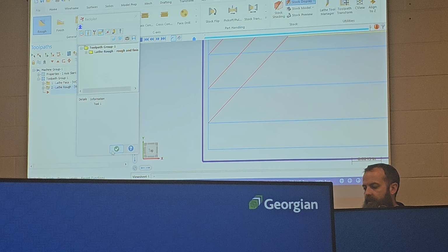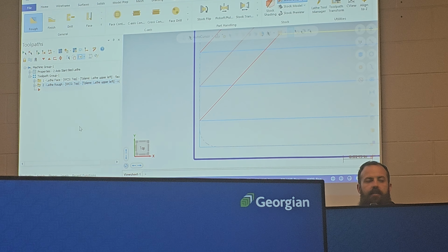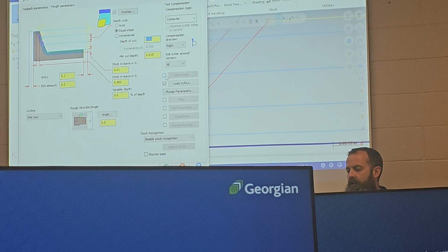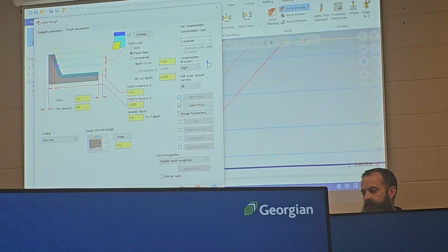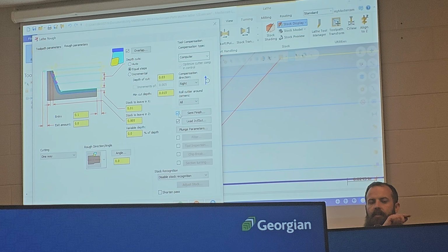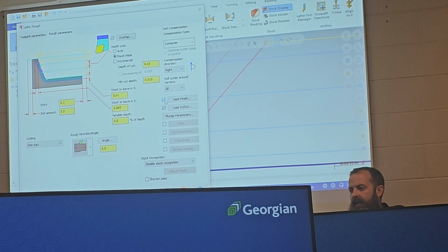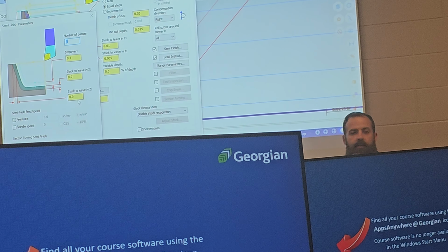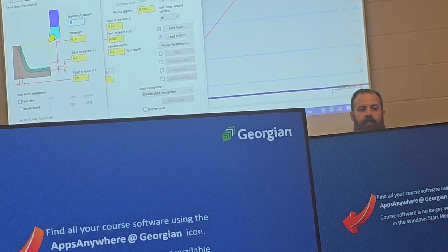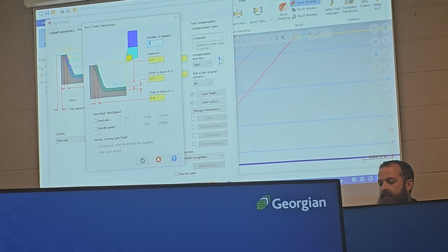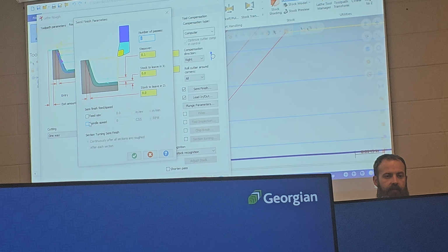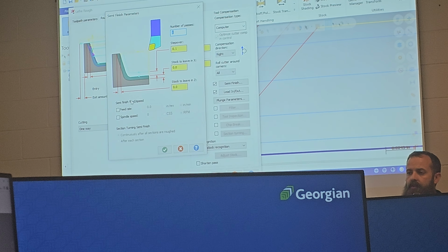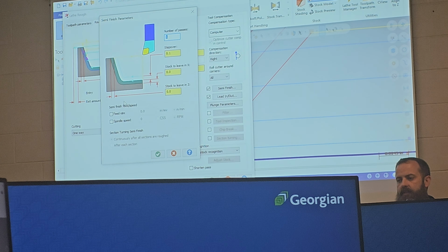The last thing we're going to do is now use this toolpath to also finish those. If I go back into it, and I check this box, semi-finish. Okay, it's saying take 1 pass along the entire profile at the end, and once I access this menu, if I still want to leave material on for another tool, I can do that. The other thing I can do is adjust the feed and speed. Okay, so roughing, I might want to feed very quickly to get the material off. Finishing, I probably want to go a little bit slower so that it looks nicer.